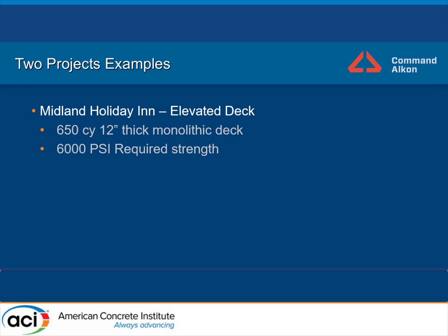The building was left idle since 2015, and they're completing it, and because of the change in the building codes, they had to go with a 12-inch monolithic second-floor deck to accommodate the HVAC system without extending the entire building by 30 inches to increase their beams thickness to accommodate the HVAC. So A, we're pouring in the middle of the night. B, I'm in Lubbock, Texas, because I had other responsibilities in Lubbock. It's being poured down in Odessa.